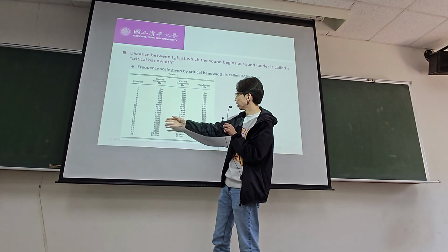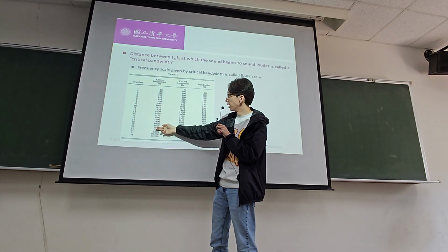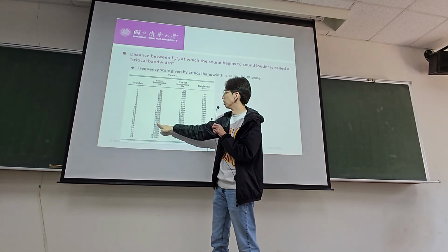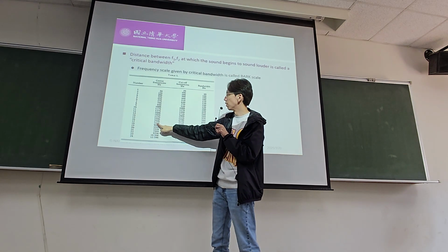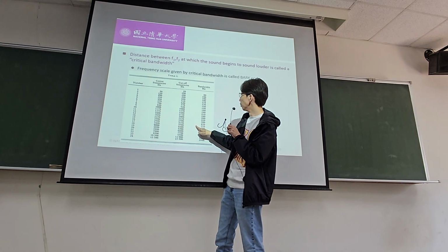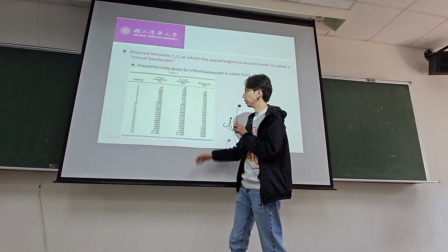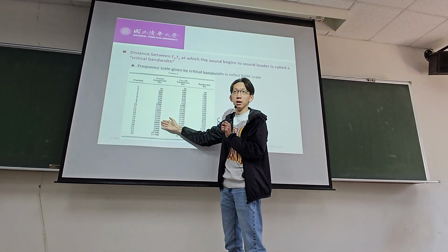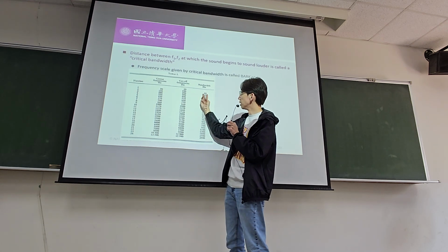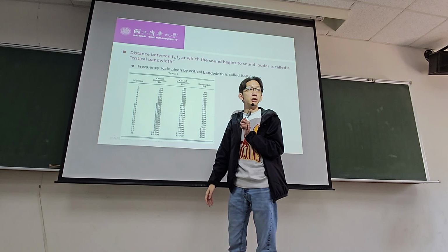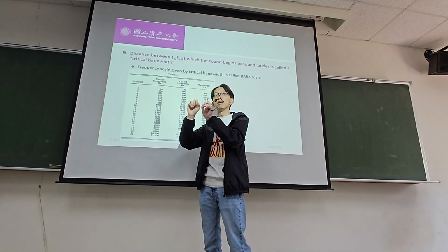Okay, and then as it goes along to higher frequencies, say here, the 17th has a center frequency at 34, cutoff frequency at 37, with a bandpass bandwidth of 450 hertz. So again, you can look at this scale. They are not linear in scale. The cutoff frequency and the bandwidth are also non-linear. This is purely by experimentation, by changing F1 and F2.